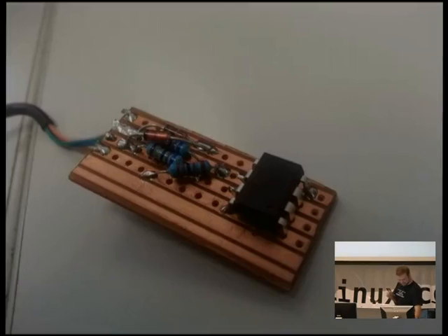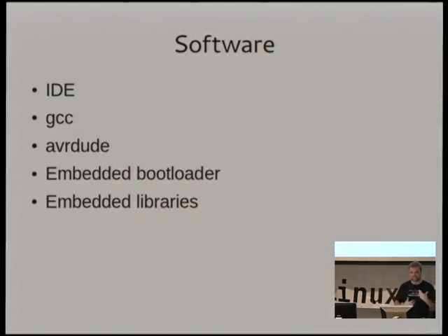Anyway, moving on. So going back to the software as the next step. It's got the IDE. The IDE really actually calls down to GCC to do the bulk of the compilation. And from there, it calls it over to a bit of software called AVRDude. I'm sure there's a good reason for that. To actually flash the firmware into the chip. So when you do your Control-Shift-U or whatever it is in the IDE, and that does the compilation, that's using GCC, and it does the flashing, and that's using AVRDude.